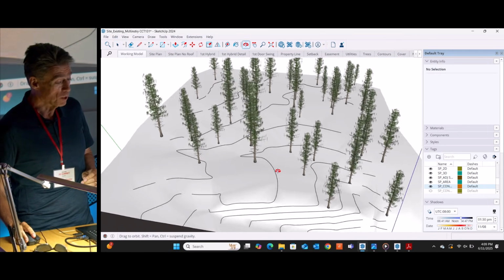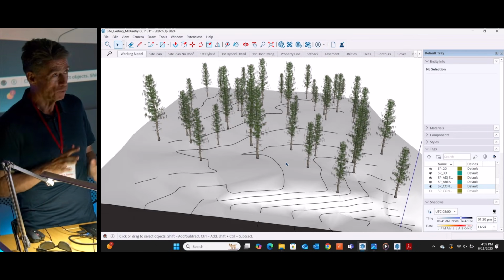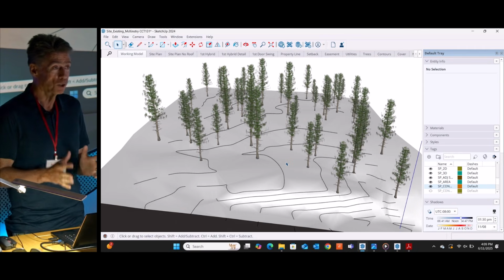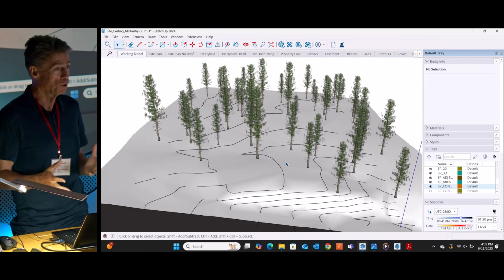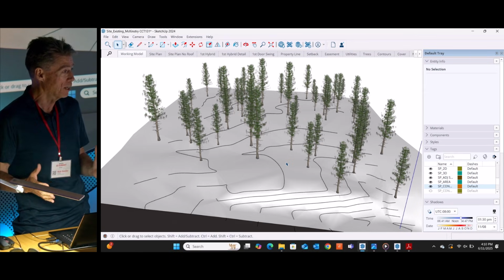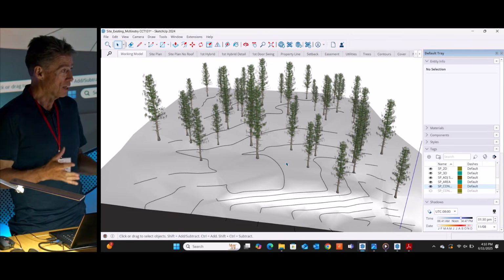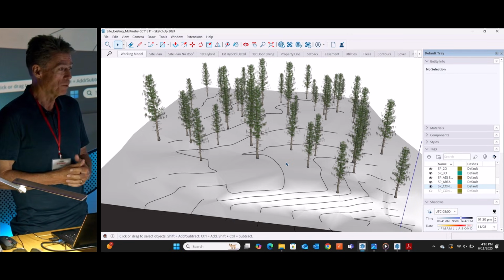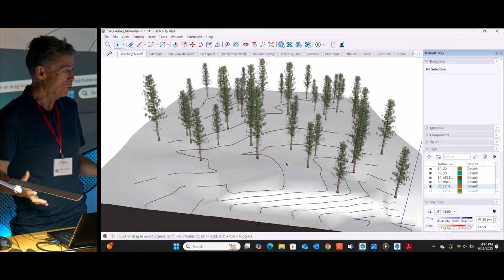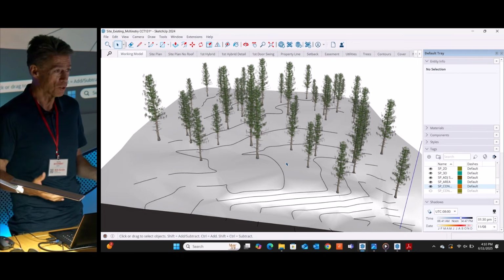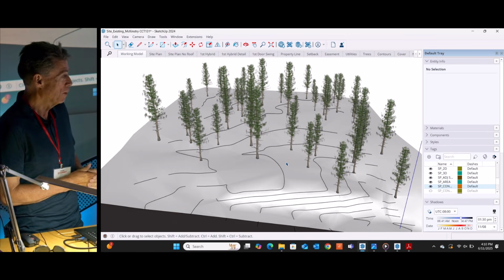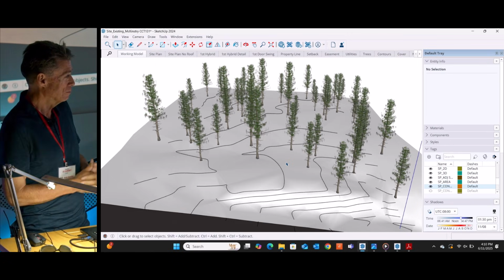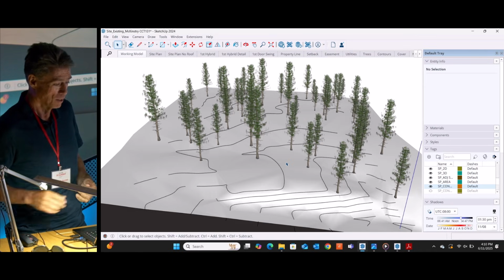But my design process, what I'll do is I always look at, there's very unique things for how we design in snow country. A large one is, as I mentioned, access to the site, positioning of the home for solar exposure, as well as how it will deal with snow migrating through the season. When I say migrating, sliding off the roof, things like that. So you have to be very cautious of what happens with all of that snow as it melts or if it moves. So you don't want it where it's going to hit people or hit cars, because it'll destroy cars, kill people, injure people. And you don't want to have a driveway where you park your car, come out, and it's down the driveway. I mean, this stuff really happens every year.